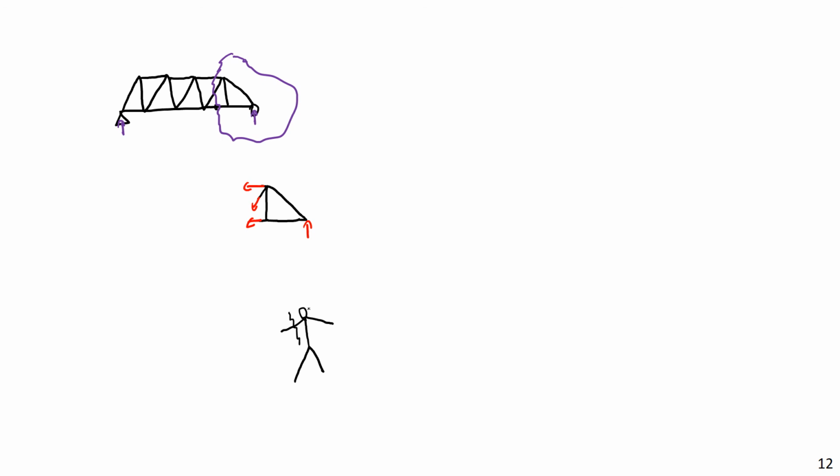And so the same goes for my entire body. No matter where I cut sections out, there would always be some force revealed to keep that object in place. Or if I'm looking for a less grisly example, a common one I use is desks and tables. I'll say, what if I were to come along with a great big saw and cut the desk in half? Well, there would be internal forces revealed, and there would be forces required to keep this thing in balance. And those forces required to keep that thing in balance happen to be exactly the forces present in the real body.